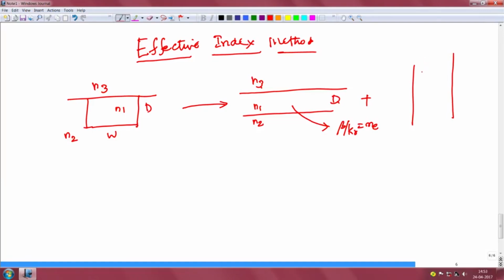It is only a symmetric slab waveguide rotated 90 degrees, of width W and refractive index N2 in the cladding region and N effective in the guiding region. So, the N effective obtained in the previous section is substituted for N effective of the vertical slab. This can be called a depth-wise asymmetric slab waveguide, and this is a width-wise slab waveguide.